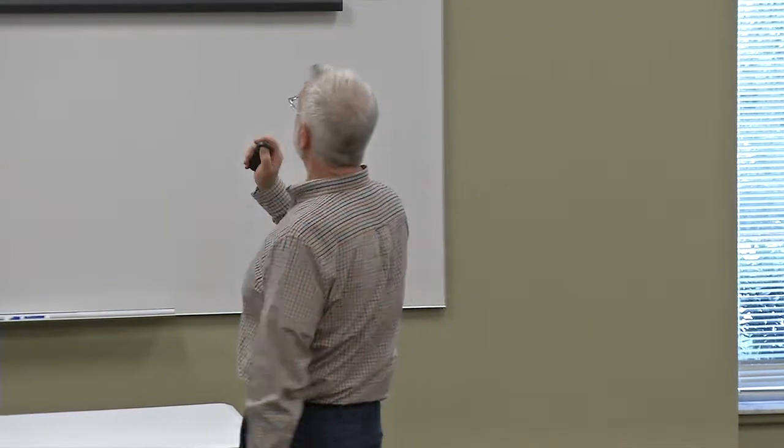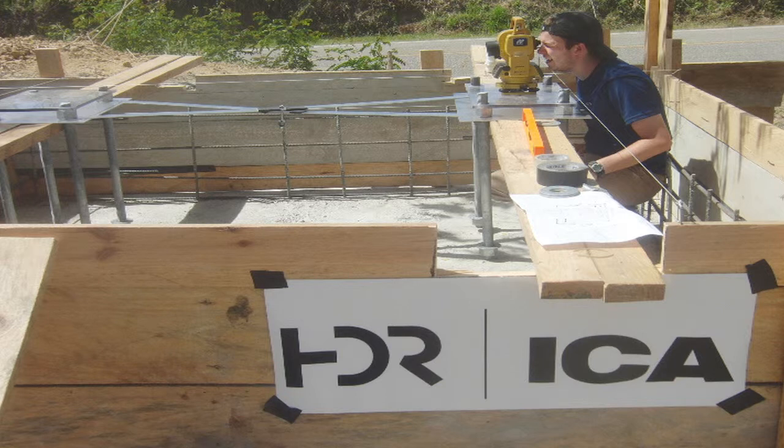Then we've got a second problem. The second problem is as we sight across to the other side of the road, we've got to be sure and hit the other pedestal. If we don't hit the other pedestal, we haven't done our job. Okay, so that's what Daniel's doing here. We're sighting across to a line right here in the middle of this plastic plate that I showed you earlier, that represents a line connecting the two bolt groups.